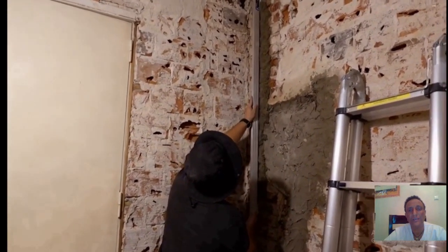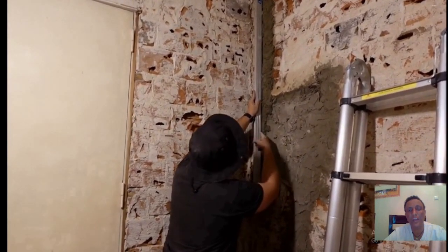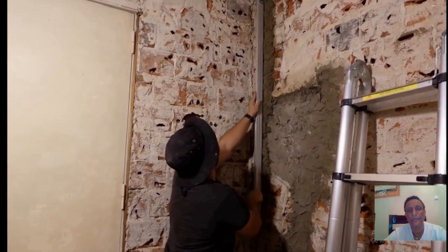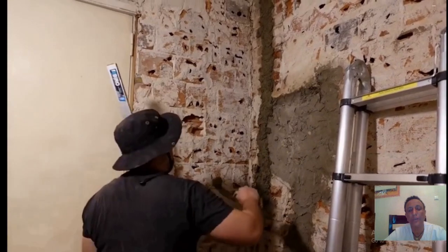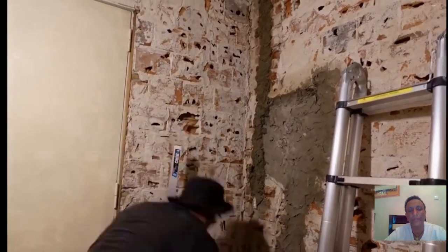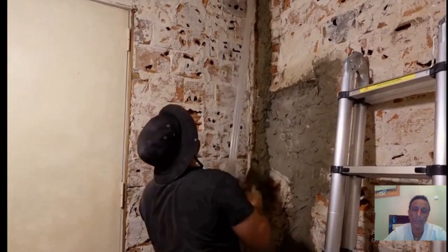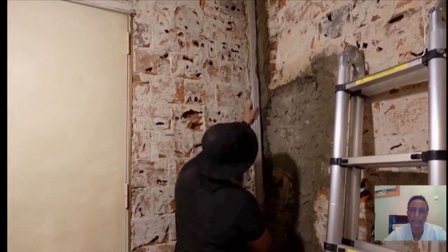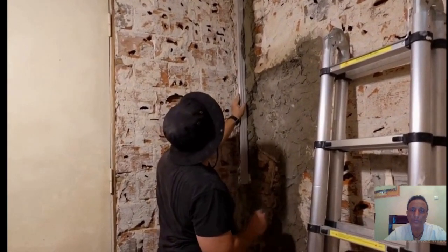The dots are used as a guidance or a reference line to make this screed. Making the screed level by using a straight edge. Filling the mortar to create the screed between two dots. Making it flat by using a straight edge.